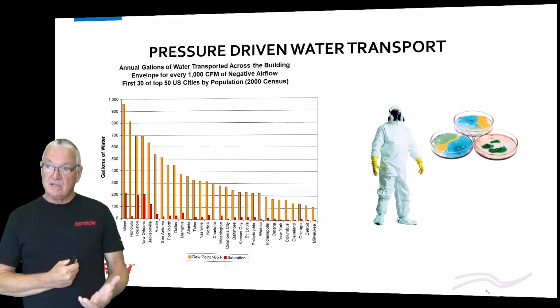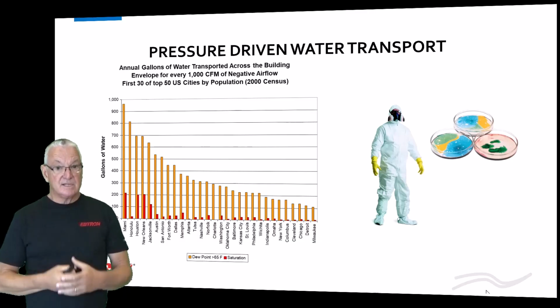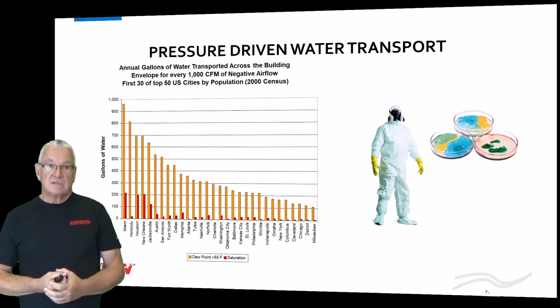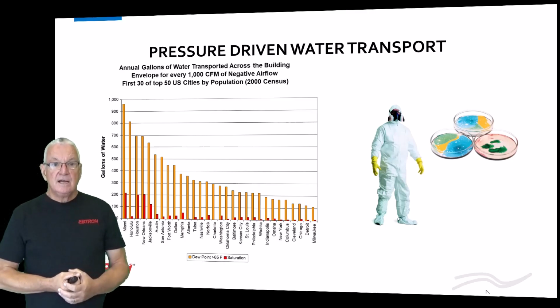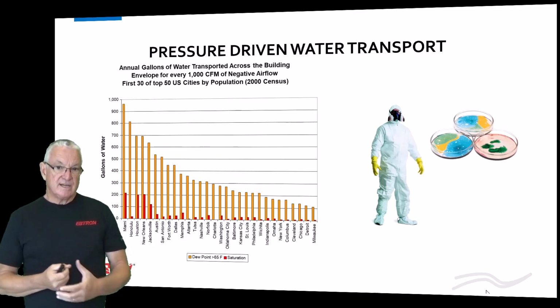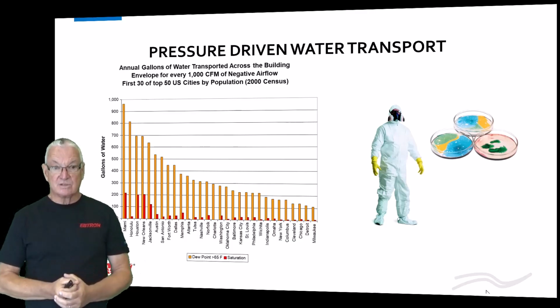But I go into these buildings down in Florida where they turn off the outdoor air during unoccupied periods, but they still have facility people in the building, and they're still running toilet exhausts, and so there's a problem there, okay? And then the condensing moisture was the darker orange, almost red color, I guess, which shows, basically, just go ahead and dump some water on the walls.